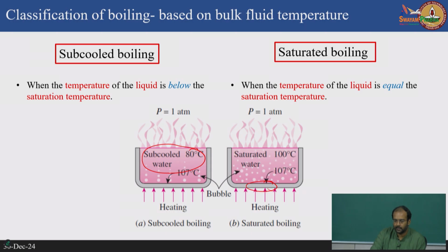So you have to understand that subcooled boiling and saturated boiling can produce completely different boiling mechanisms, because in the case of subcooled boiling, the boiling is initiated right at the interface of the solid and the liquid in terms of these large bubbles, which then have to rise, okay, as you keep increasing the heater temperature. As they go up, the temperature of the bulk liquid is much lower than saturation. It does not promote a state where the bubble can remain in vapor state, so they again collapse. So they cannot reach all the way up to the liquid-vapor interface.